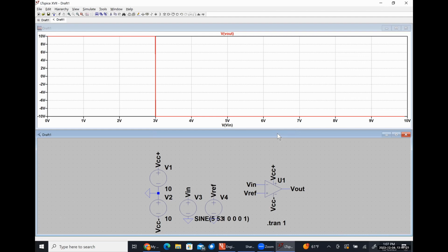Still not working? Let me see what you did. Yep, trying to keep up with you. Holy God, yes, you have tons of currents on there. So let's delete all the currents, so if there's an I in it at all. I just clicked on everything at that point because I missed a few steps. I was trying to catch up with you. So the only thing that you don't have on here is the thing you need. You need the output voltage.